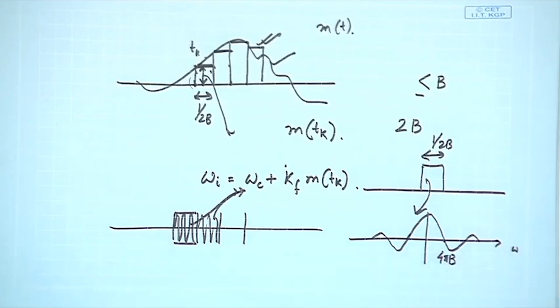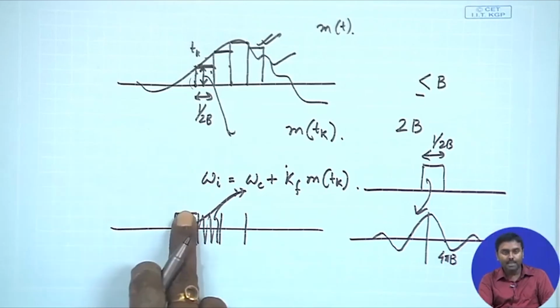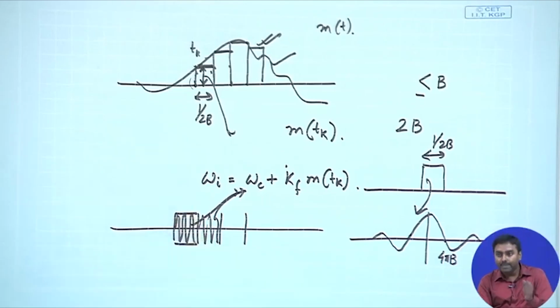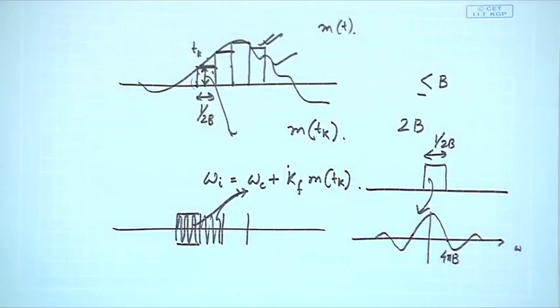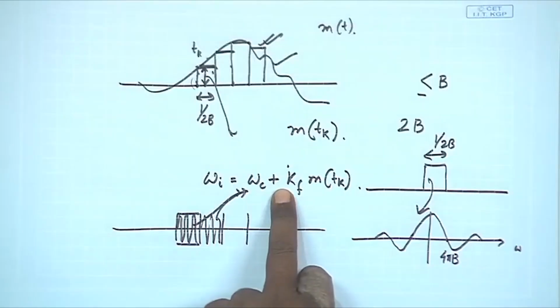But what is happening is that the particular pulse is getting amplitude modulated; it is a pulse and I am modulating it with a sinusoid of this frequency. So immediately this will be shifted; modulation means that pulse is getting shifted in the frequency domain to this particular frequency.